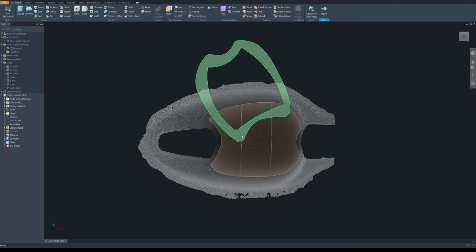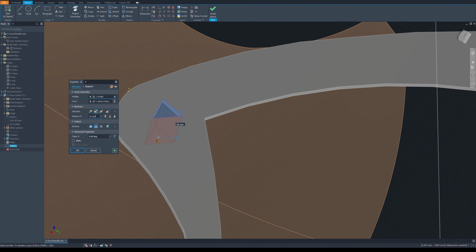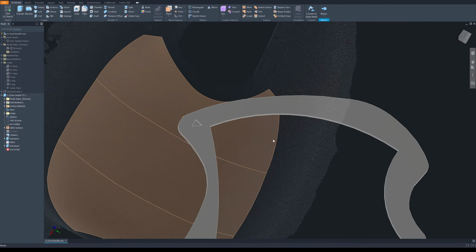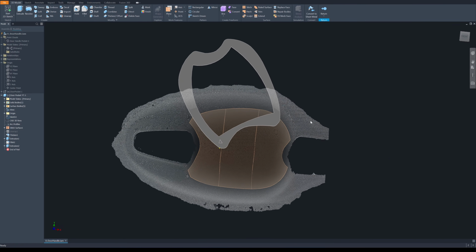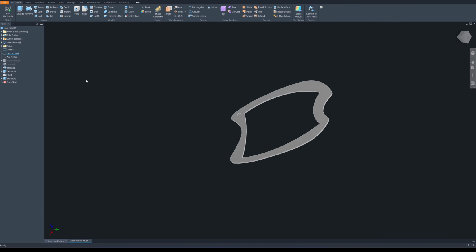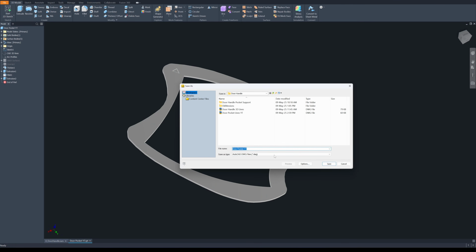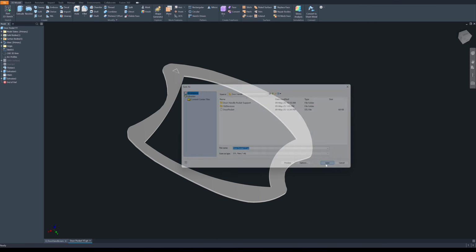Yeah, this one is up. I'm going to put some mark here. This one is up, a small triangle. I'm going to cut it to 0.4, just 2 layers. It's quite difficult to tell, isn't it? Yeah, this one is up. Okay, next I'm going to export this one. File, export, cut format STL, click on save.